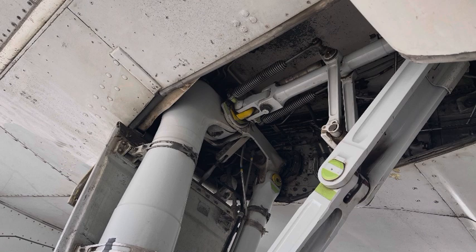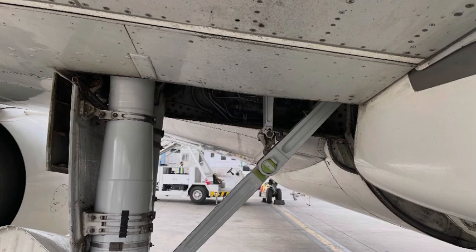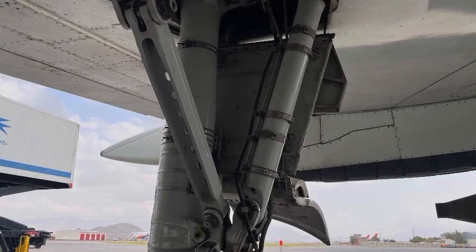Besides the shock absorber mechanism or shock strut, which is the main structure of the landing gear, mostly we have some other linkages which support the rigidity of the landing gear. So it supports the landing gear to be rigid without having any play. Mostly in Classics we have two other linkages, which are the drag strut and the side strut.